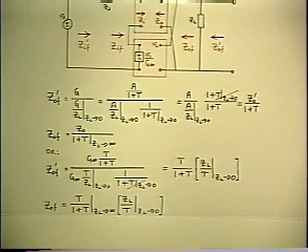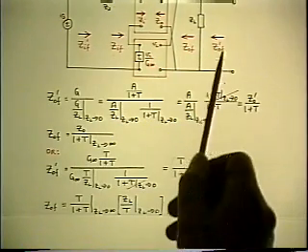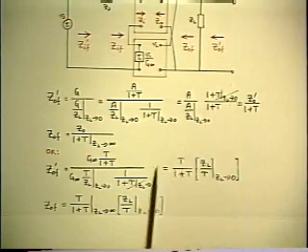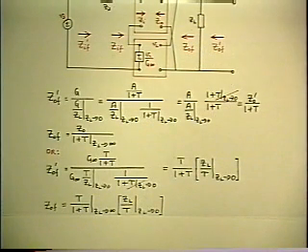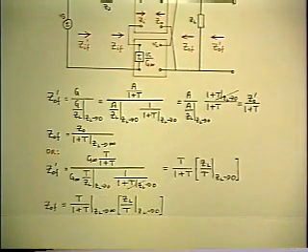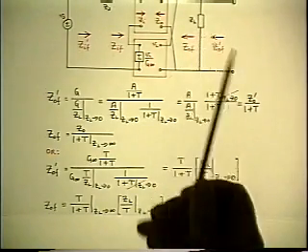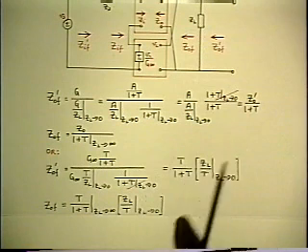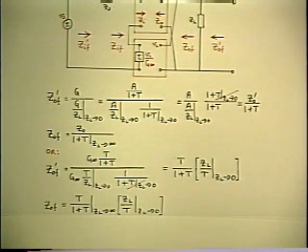Yeah, they're almost the same. Therefore, the inside and outside output impedances are almost the same. What does that say about the value of either one of them relative to ZL? Well, insensitive because of what value? Very low. They both must be much smaller than ZL for them to be almost equal, because the ZL in parallel is the only difference.